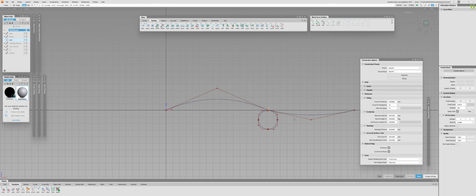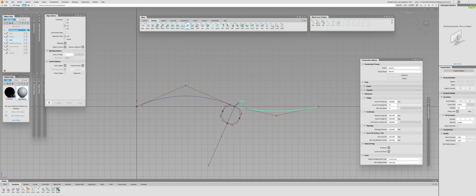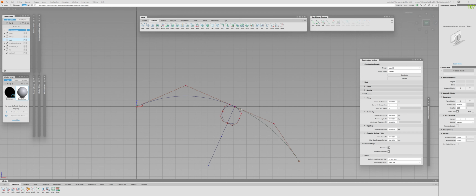So it's just pretty much what Alias does. You have the point of connection, there is a curvature, you need to check it. It creates a perpendicular line, places a circle, calculates the radius of the circle to this side, and then another one to this side. If they are spot on, these radiuses are equal. If they're not, there is a slight deviation. Now it takes these two radiuses and compares the two using a specific formula.